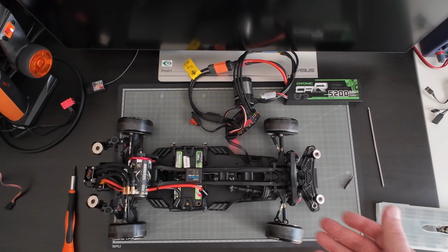Okay, so now just a recap of what we learned today. If you are after an analog setup, then the only thing you really need to pay attention to is the gyro, because you can see that some gyros cannot really fall back and send out the analog signal. And that's the only device you can really go wrong with if you are after an analog setup. Everything else will still fall back to analog and everything will be working fine, okay?